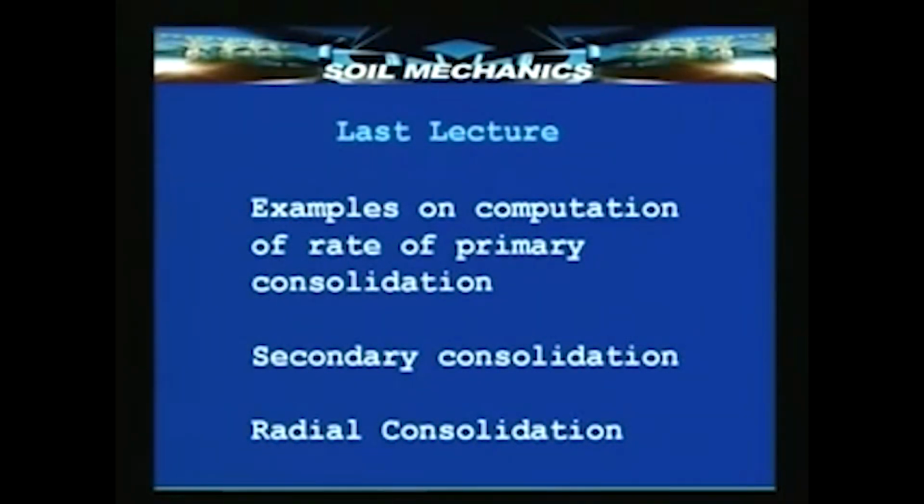If you remember, the secondary consolidation is nothing but a consolidation which takes place in the form of plastic lag. That is, after the hydrodynamic lag which is arising due to slow flow of water is completed, the plastic flow of the particles and their readjustment starts. Load remaining same, this readjustment goes on for 2 days, 3 days at times, and that is the secondary consolidation part. We also saw an exponential equation with the help of which we can compute the magnitude of this secondary consolidation. And lastly, I introduced 3-dimensional consolidation, the concept.